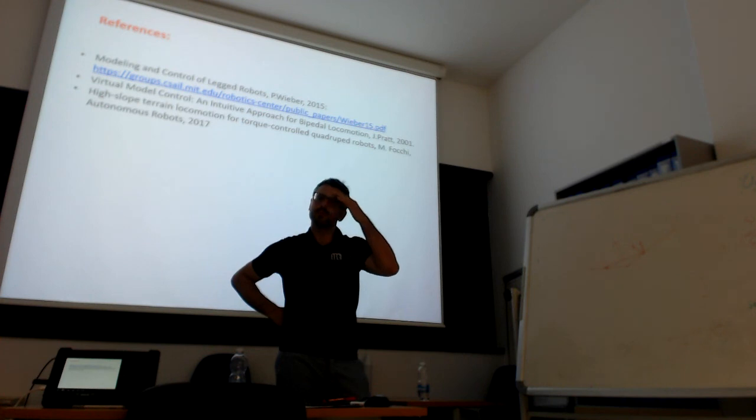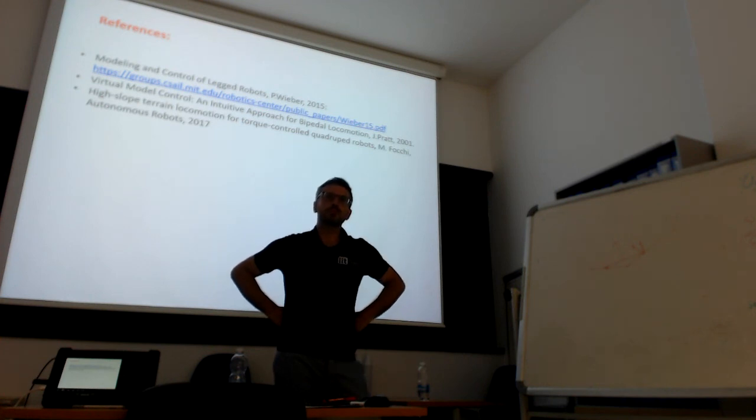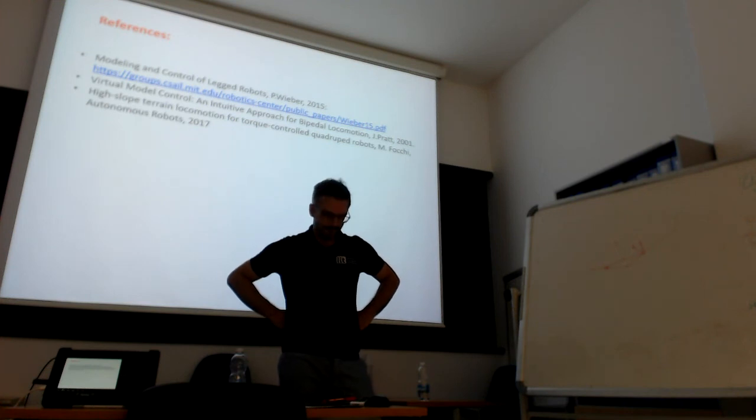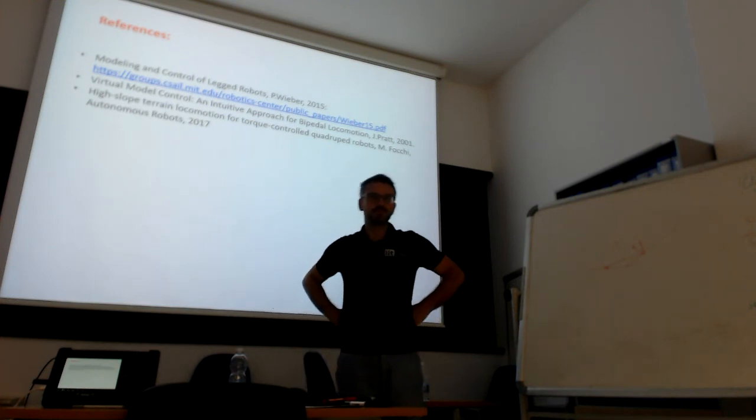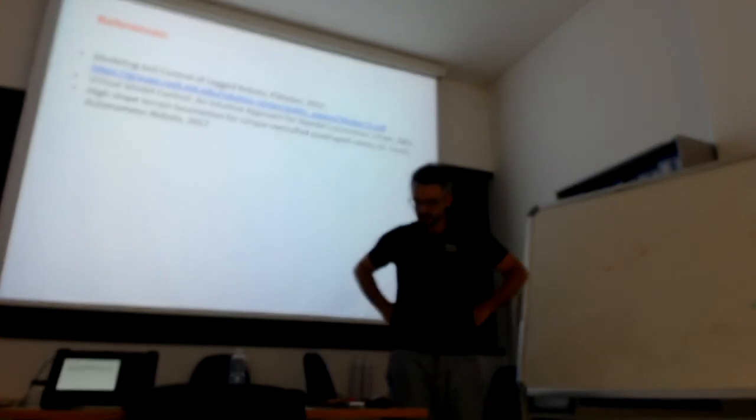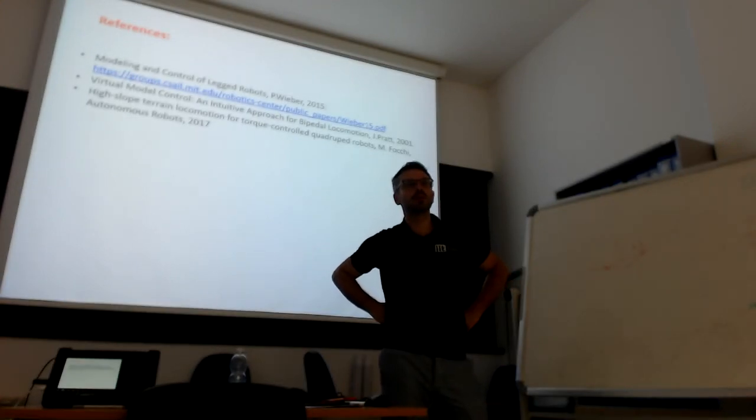Because maybe, for instance, when you use optimization techniques, the reason that you add the friction cone is not only to stay right in the middle, but also to go to the boundaries of the friction cone and exploit that value to do some dynamic motion. Do you think that could be an energy efficient criterion? So it depends what you write in the cost function, of course.